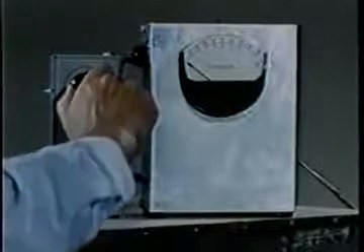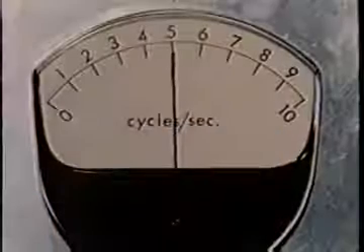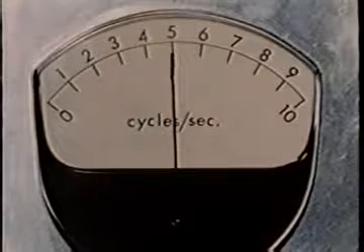In order to find the frequency response of amplification, we put in sinusoidal disturbances which we can control. We start the wave maker oscillating at 5 cycles per second, at 0 airspeed, and observe the waves as they travel away from the wave maker. With the tunnel running, but below critical airspeed, we don't notice much change in wave damping. As we increase the airspeed and pass critical speed, we see the waves grow.